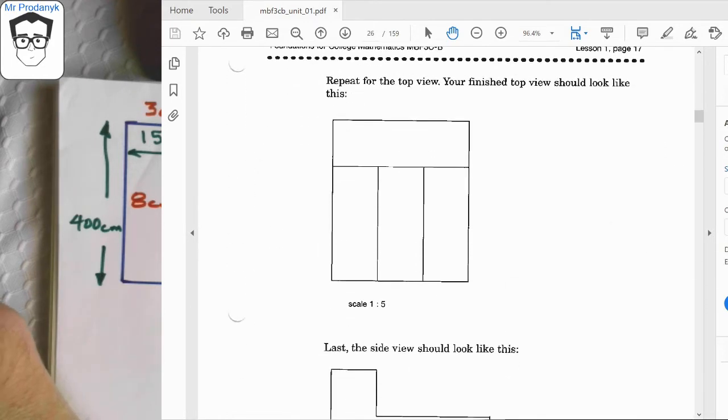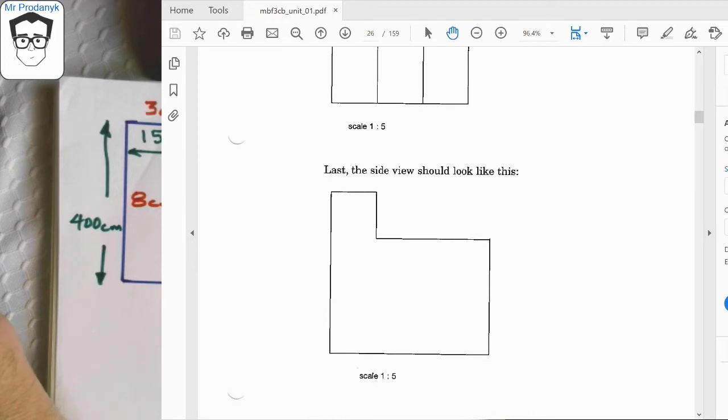Okay. Now imagine rotating this and we look down upon it from the top. We would see something that looks like this. So again, a straight on view from the top. That's the orthographic idea, we're looking straight on, the ortho prefix. This is looking straight on from the top, looking down. We can see the seat indentation in the middle and the higher back at the top.